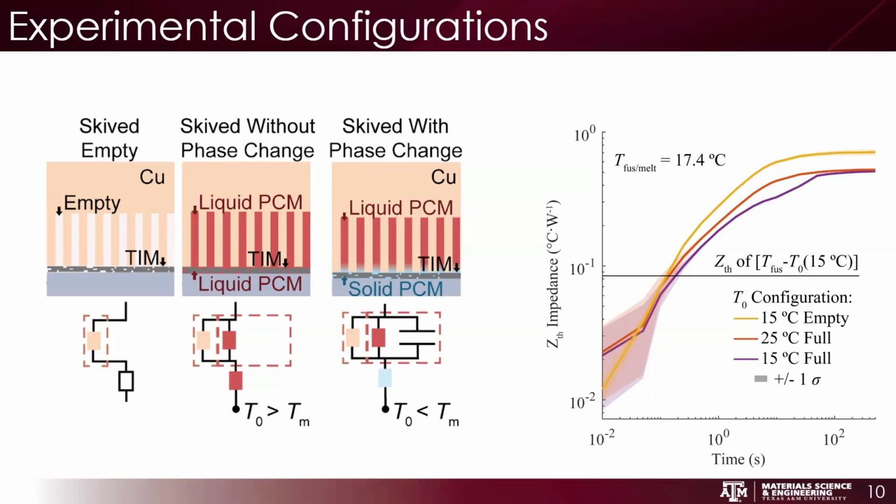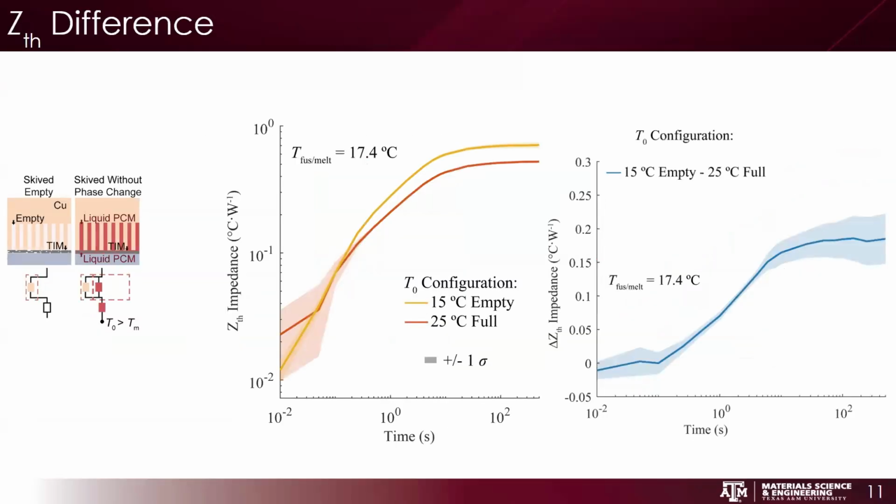So it's initially solid, and then we're putting in energy, and there's a temperature suppression around the melting temperature, and then it reaches the steady state. Since the thermal conductivity at solid and liquid is relatively the same, these semi-converge within about 5% of each other. So what we can do then is we look at the differences in thermal impedances to see if we can kind of isolate the thermophysical properties of adding PCMs to these systems.